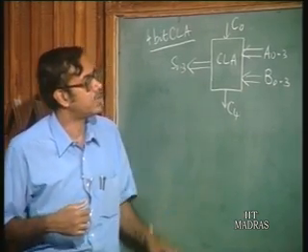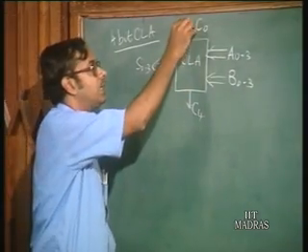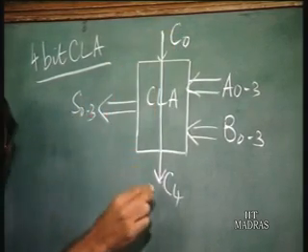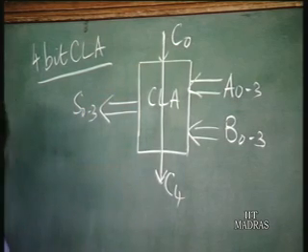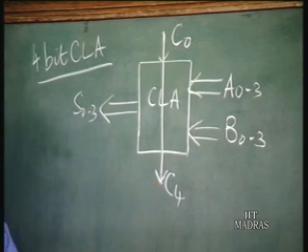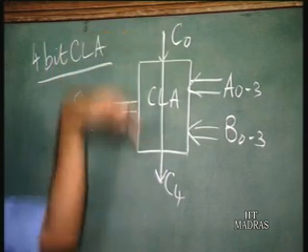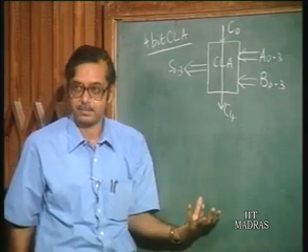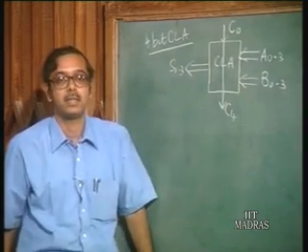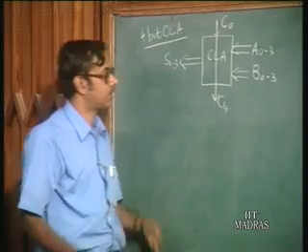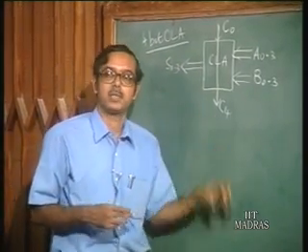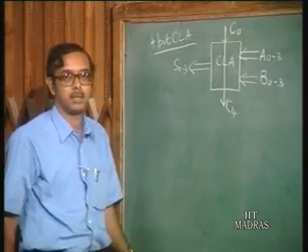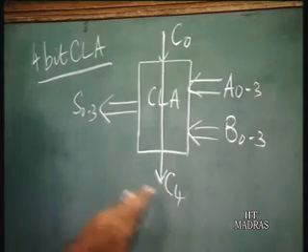Here we had already seen the structure, and we had seen that the most critical path is the carry C0 to C4 path. When you have 32-bit adders, you have 8 such adders, and this C0 must propagate all the way to the last adder in order to obtain the full addition. So, this is a very critical path, and the delay in this path must be reduced as far as possible. The so-called carry propagation circuit must be fast enough. And we have also seen the expression for this carry output here. What is it?